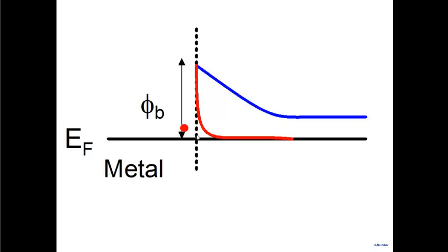Tunneling is very, very sensitive to the thickness of the barrier. You may be wondering why it doesn't start from here and go directly here. Well, because it's very thick. It's extremely thick. We just calculated at 5 times 10 to the power 16, the barrier thickness is how much? 1000 angstrom. Tunneling is exponentially dependent on the thickness of the barrier. So it's not able to tunnel. It can't go from here to here. So it has to go over the barrier.